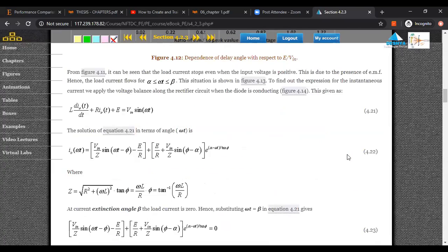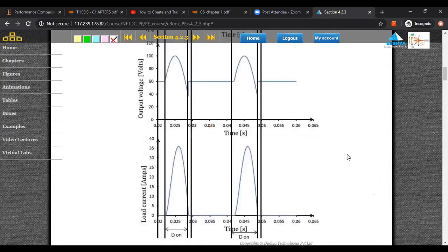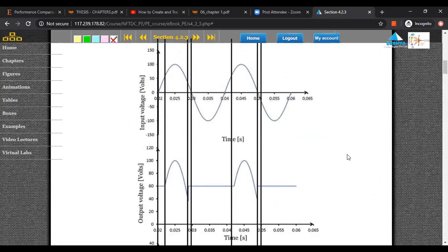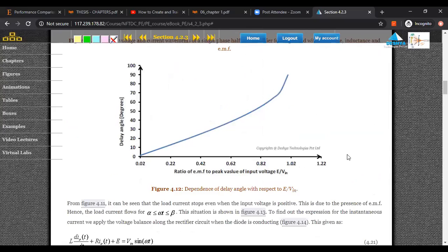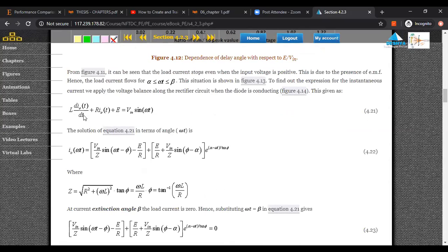It's very important to become very knowledgeable in whatever you do. So now the equations. The graphs, I'll come back to when I discuss the animation part. But the equations, the circuit equation, is simple. In the earlier case, V is equal to the voltage across the resistor plus the voltage across the inductor, plus the EMF in this case, because it's a series RLE load. So the input voltage is divided across the EMF, resistor and inductor. Fair enough, right?